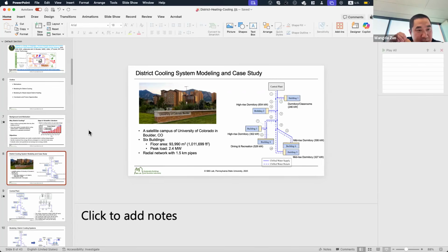Okay, another comment: how different is the landscape of district heating from Sweden to the US? Steam is still being used for heat in the US, and I guess the amount of heat loss would be quite large compared to water-based systems. Yeah, I agree. I would say steam-based heating is really a legacy system, right? It's definitely not that efficient compared to hot water-based or even ambient loop systems. But the challenge is that if you want to convert the infrastructure, it costs billions of dollars. Not everyone has the money to do that kind of conversion. So that's why it's still largely used in the US.